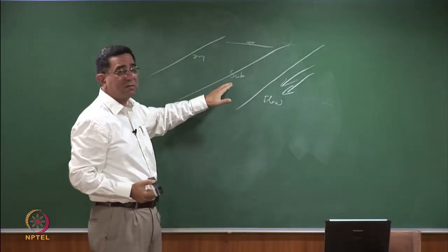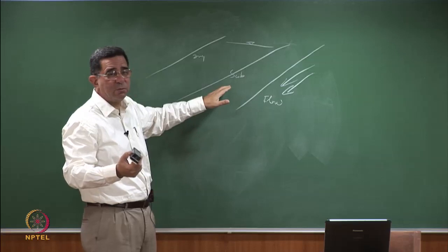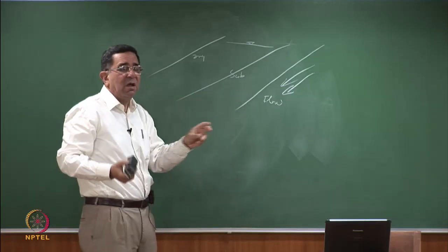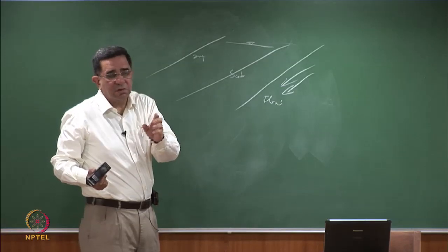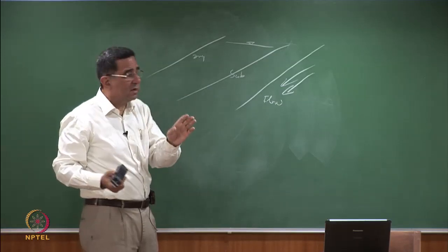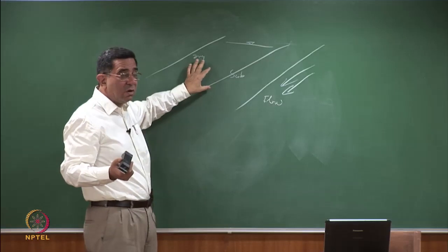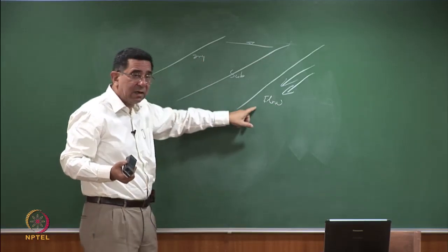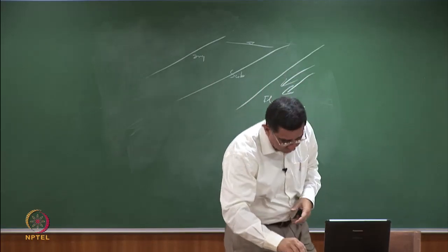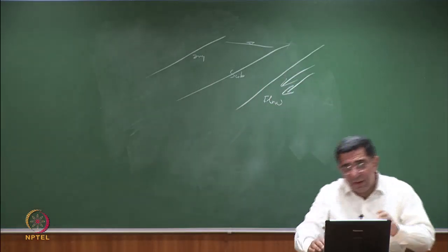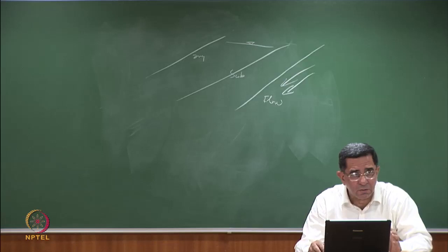In these two cases, it's tan phi dash by tan beta. It's possible that the submerged soil may have a different phi dash by a few degrees. If it's in sand, sometimes phi dash dry may be 35 and phi dash saturated may be 32, 33. Not necessarily, so sometimes they are identical. But that depends on the difference in the phi dash. Here, the factor of safety becomes gamma b by gamma t. So these are the formulae which we use for the purpose of understanding infinite slopes.